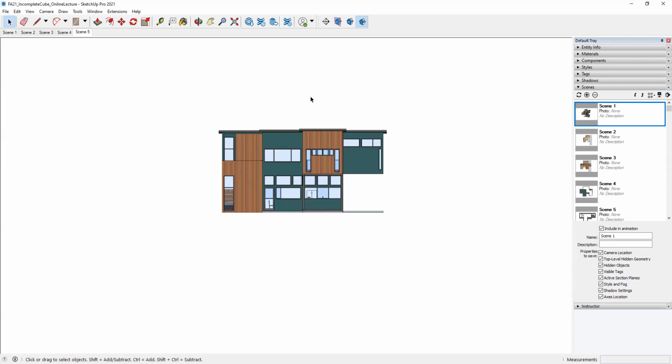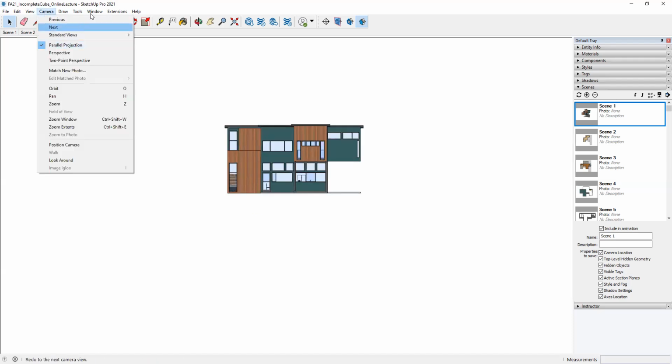But an elevation view is a vertical view. It's a view of the actual surfaces, the vertical surfaces of the building. And again, the benefit here is that we could take measurements, heights. So we could say, hey, this window should be placed, and then show a dimension 42 inches from this height. And this window is X amount of feet high, and so on. Now we're still in parallel projection.